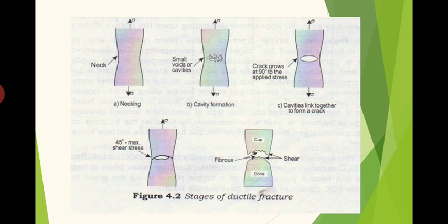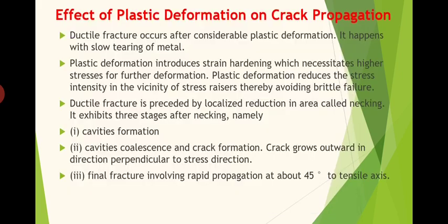In which region the neck forms actually depends on in which region more stress is acting because of the applied stress. See, where some voids or cracks are there, or we can say in the weakest region, the neck is going to be formed.